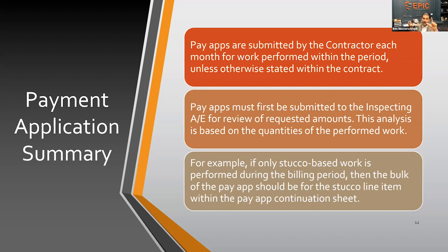Now, depending on the condition of that structural shell, you may have some unforeseen repairs. You may have cracks, you may have spalls, you may have rebar that you'll have to deal with. Those will be the unforeseens. But we still want to get individualized pricing for it because that number can get pretty big, and you don't want to be married to a singular contractor for that value. It should be a number that should be reviewed prior to the selection of a contractor.